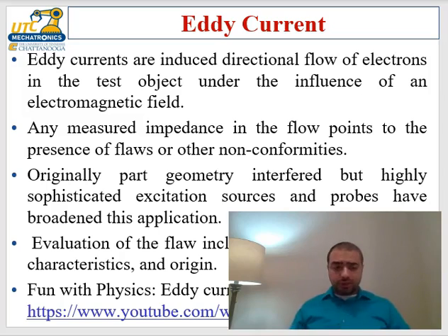By the way, there's something that is very important: the skin depth. I don't know if you've heard of that, but remember, eddy currents exist with an alternating magnetic field, in other words, an AC signal. For AC signals, the AC currents tend to distribute themselves on the outer surface, the outer shell of the conductor. And as the frequency increases, the skin depth becomes lower.